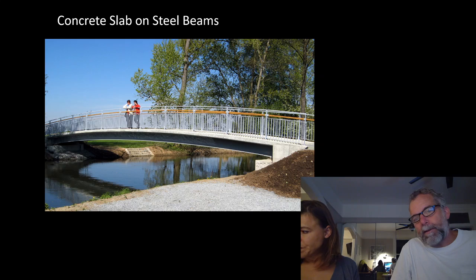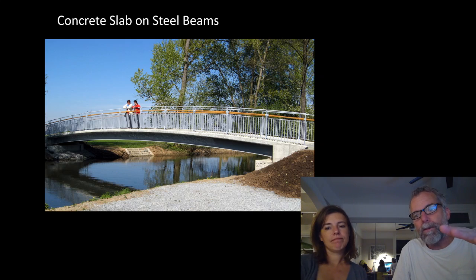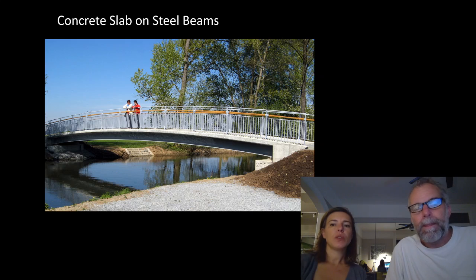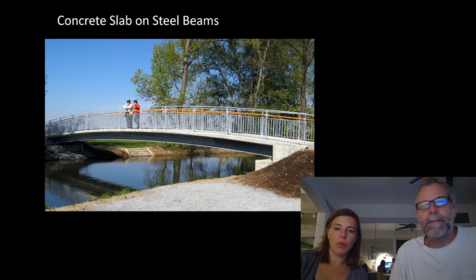And your ramp needs to be 1 to 20, so it's got to be a very shallow ramp in order to be accessible. So we try to keep it as low to the ground at the ends as we possibly can.